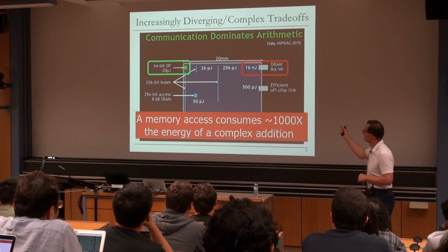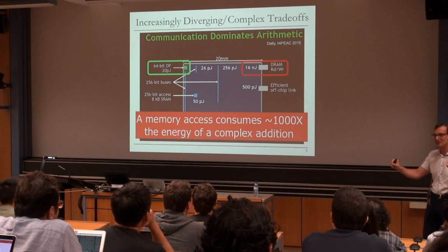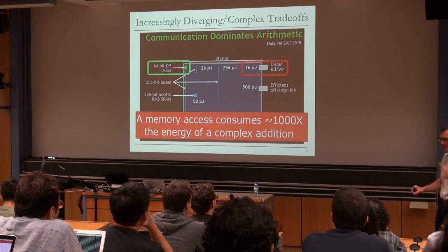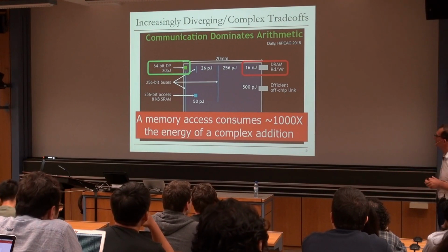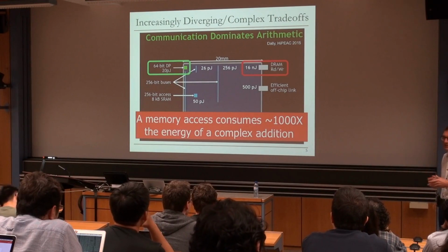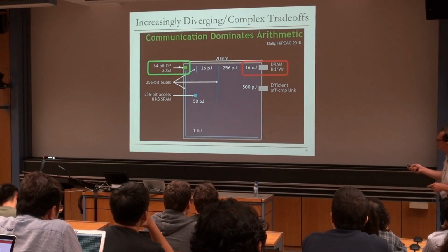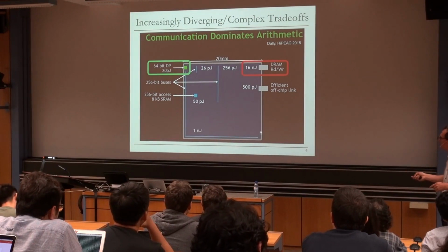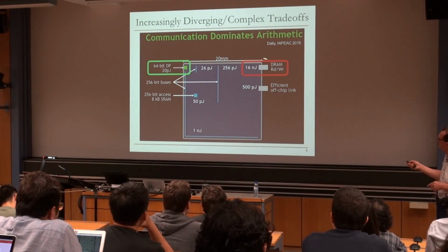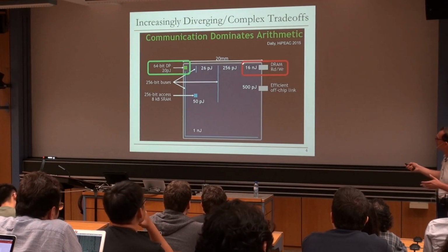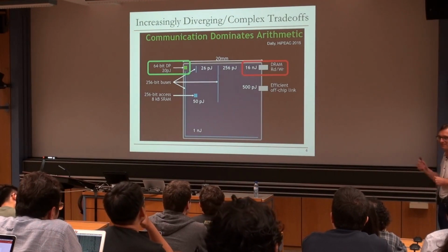So the real problem over here is going through that off-chip interconnect. Those are actually very heavy. You need to drive the interconnect, and you need to drive it back. So there's a lot of overhead in terms of energy that happens. On-chip interconnect is not very expensive. But as you can see, it depends on the distance you travel. So for example, going from one end of the chip to some other end of the chip for a 20 millimeter by 20 millimeter chip, it's 1 nanojoules. But that's still about 1 order of magnitude lower than DRAM.